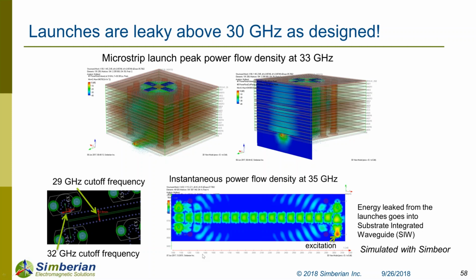Also, from these lessons learned, with the inner tray, the one that has stub resonance, even though it's a really lousy launch, it was around 32 ohms and it was designed to be 50, plus it had a resonance. Even with this resonance, we were able to accurately extract the S-parameters. So just keep them localized. That's totally better. After the localization breaks, everything becomes problematic and unpredictable, exactly. Then you have to simulate the whole board. So yes, you end up with simulation, and this is valid for via design, not just for the launch design. Again, this is valid for vias, for single-ended specifically. It's not over-designed.